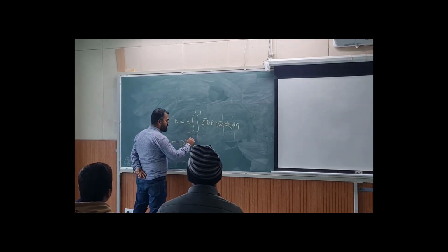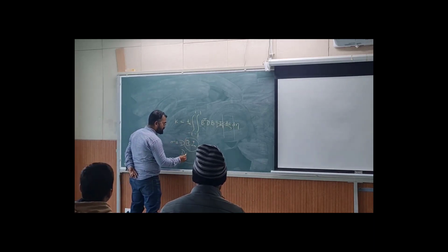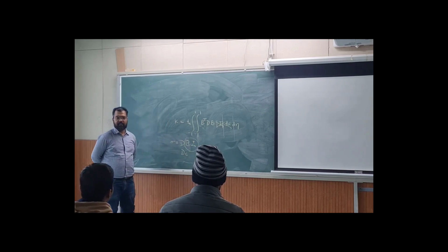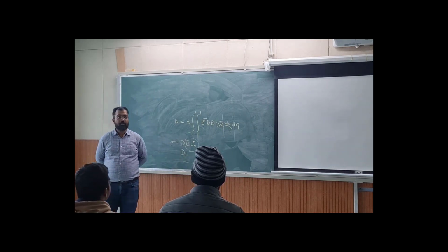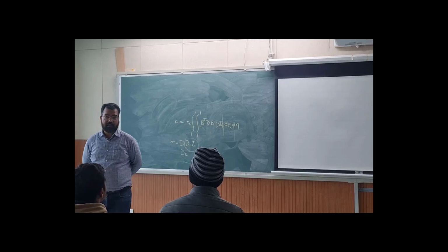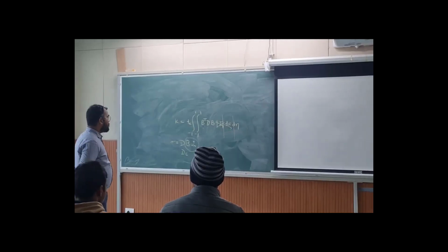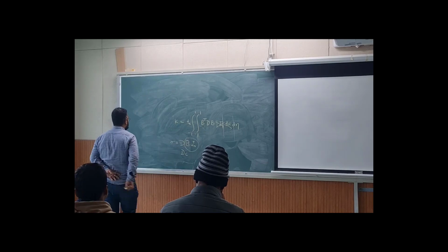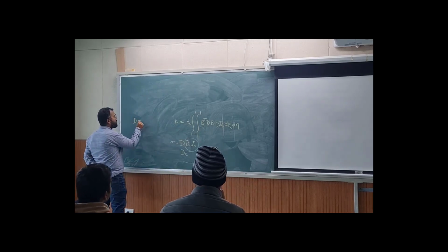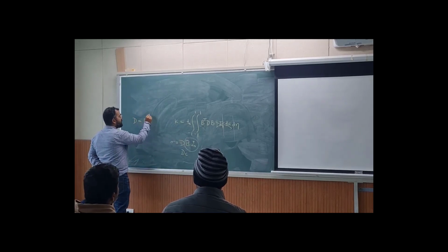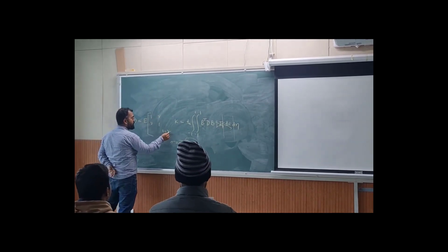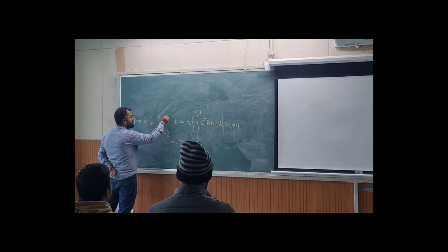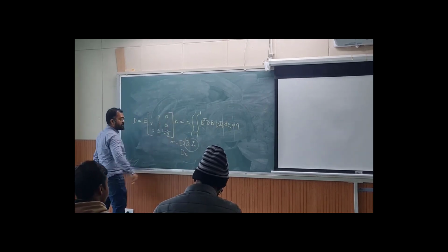And this is strain. So it's just that. So what should be D? Stress is equal to D into epsilon. What is D? Elasticity. Right? So this D matrix for plane stress will be elastic modulus into 1 mu 1 1 minus mu by 2, and the rest of the things are 0 0 and 0.